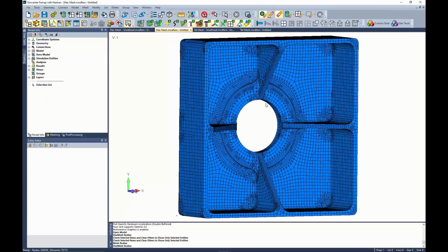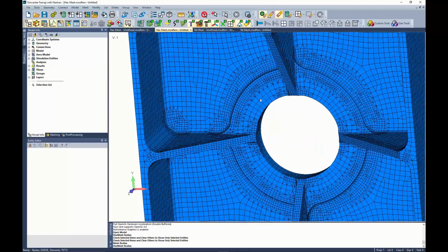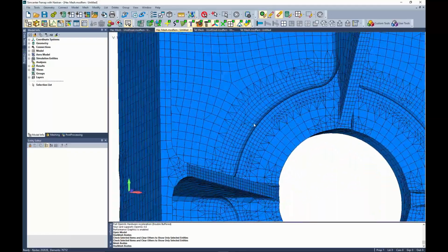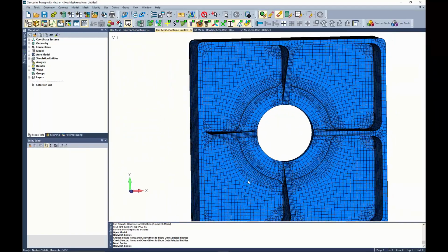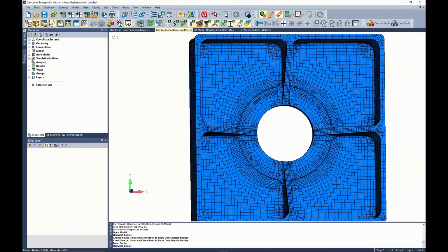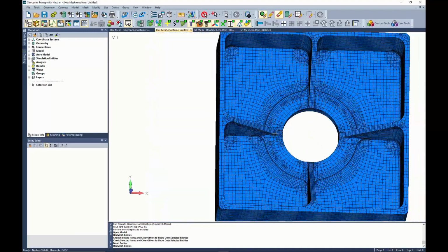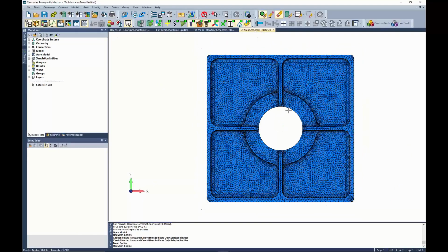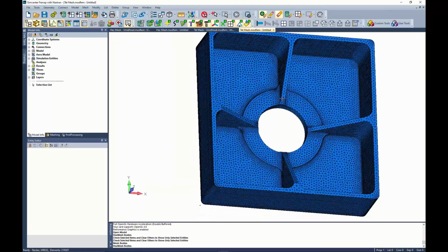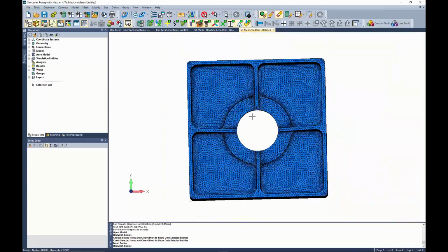But just that one command makes the mesh refine a little bit more in these fillets, and you can see you definitely do have some more Tet elements, but in the transition from Tet back to a more refined hex. But this more closely matches something that would come out of the Tet mesher if you had some sort of surface curvature refinement. Actually, yeah, something like this.